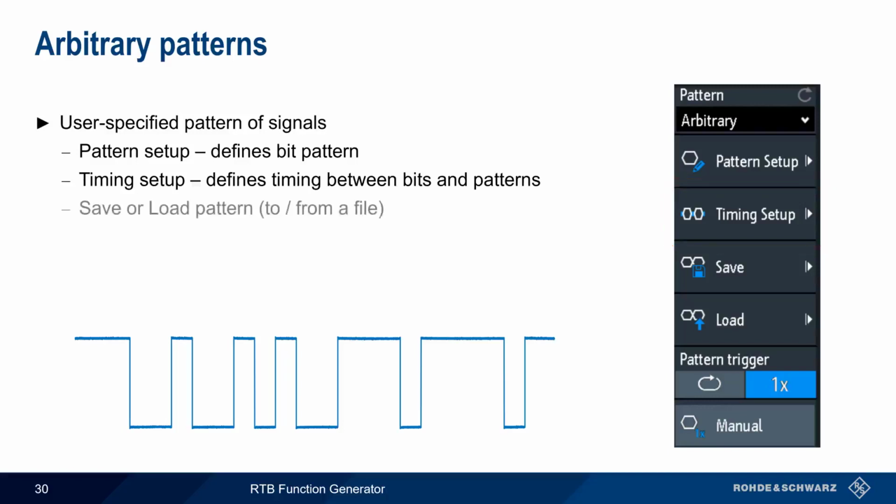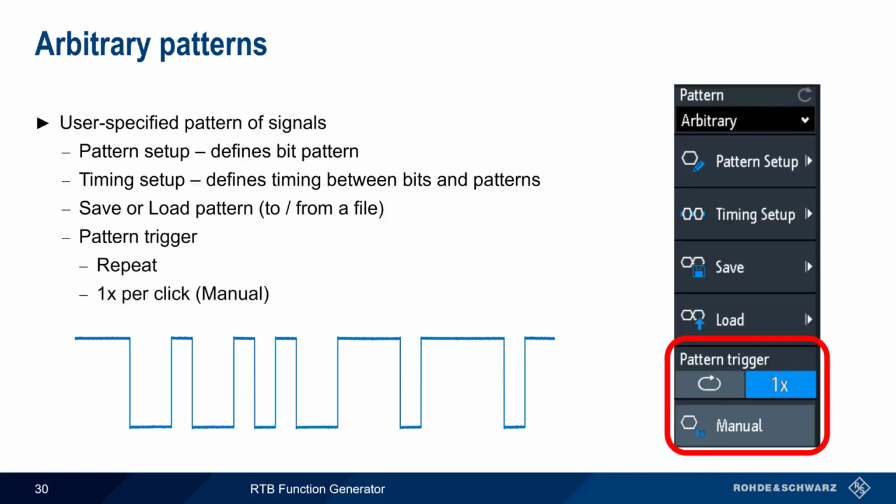Patterns can also be either saved to or loaded from a file. Finally, to send the pattern, a pattern trigger type is selected. Either repeat the pattern continuously or send it once per click on the manual button. Let's go through the creation of a simple arbitrary pattern.